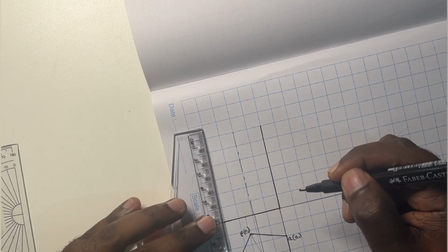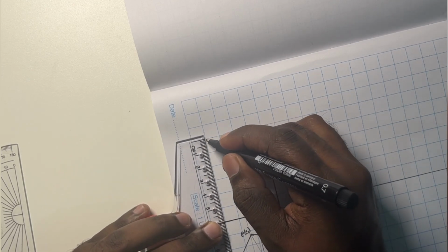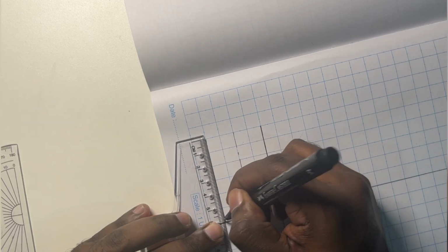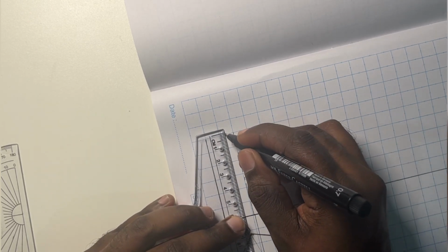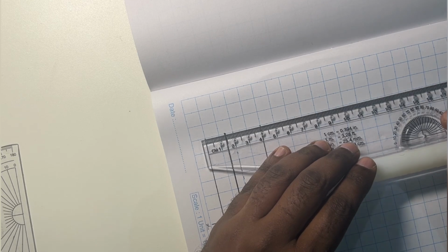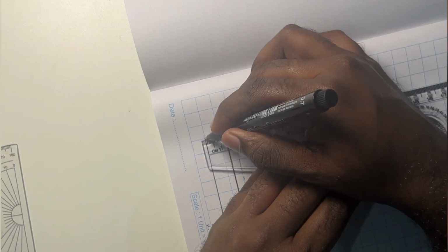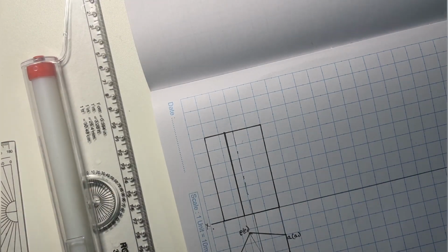So this is one rectangular edge. And similarly, the corner D. And next, this edge is also visible. So this is the second rectangular face. So I'll be able to see two rectangular faces like this. Let me complete the top face of the prism by drawing the projection line. So this completes the front view of the pentagonal prism.